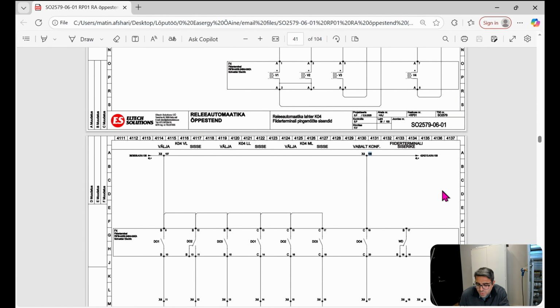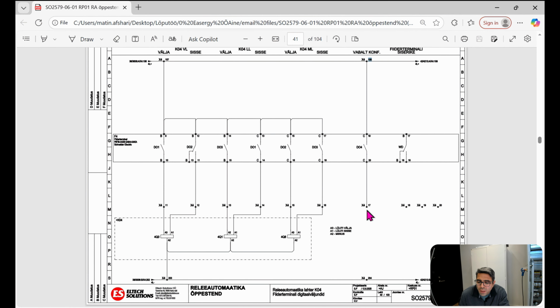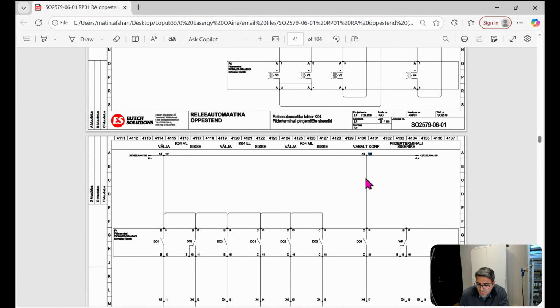But before that, we have to disconnect this here. I will show you how it's done on the terminal. And the 17 is free. It's not connected anywhere. So we just connect our wire to here, and the feedback wire, the minus side, to here, and we connect to the tester.